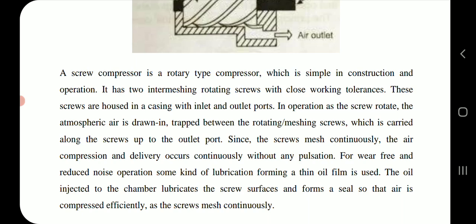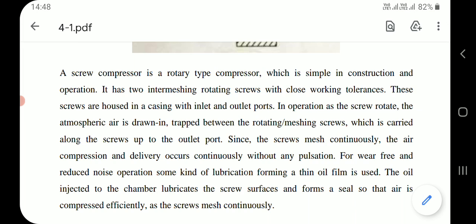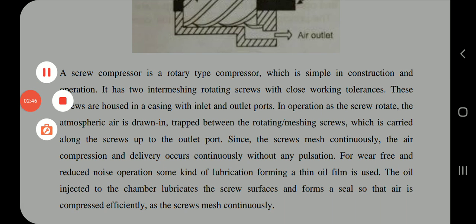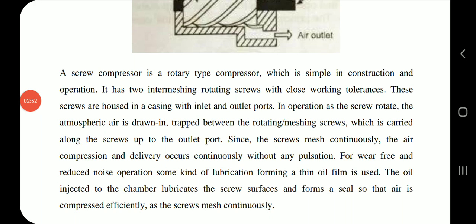In operation, as the screws rotate, the atmospheric air is drawn in, trapped between the rotating or meshing screws, which is carried along the screws up to the outlet port. Since the screws mesh continuously, the air compression and delivery occurs continuously without any pulsation.